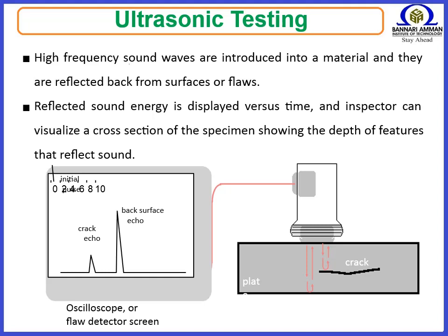Ultrasonic inspection techniques are commonly divided into: pulse echo and through transmission, which relates to whether reflected or transmitted energy is used; and normal beam and angle beam, which relates to the angle that the sound energy enters the test article.